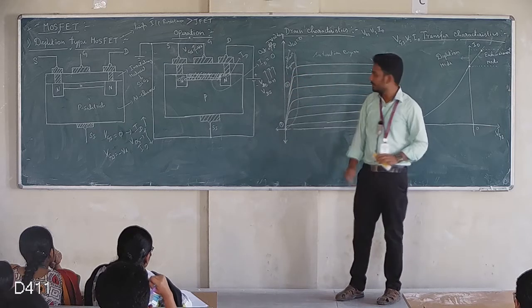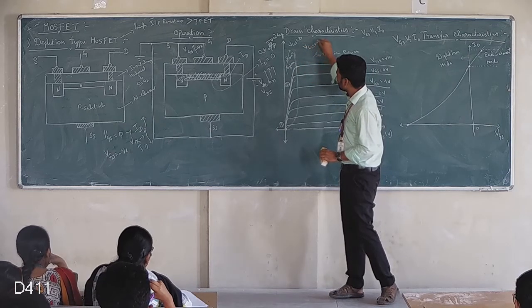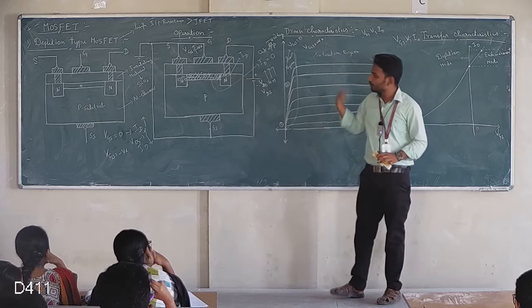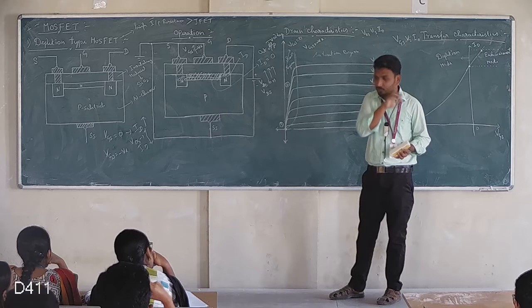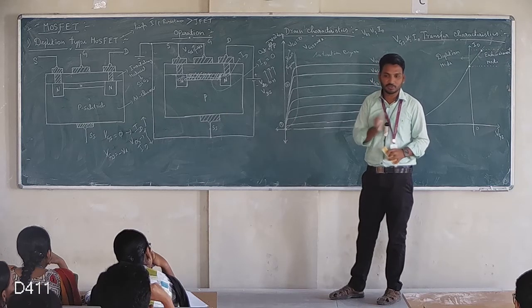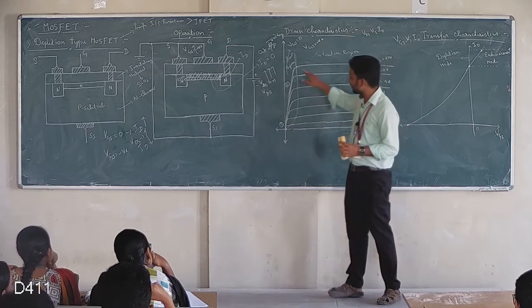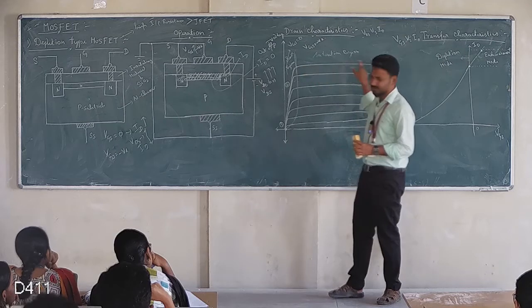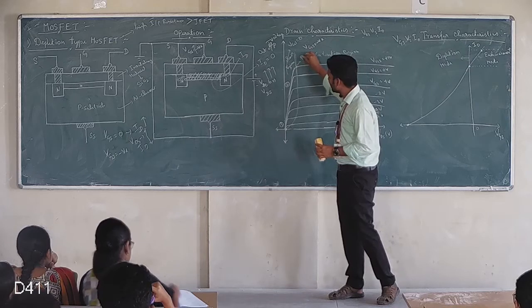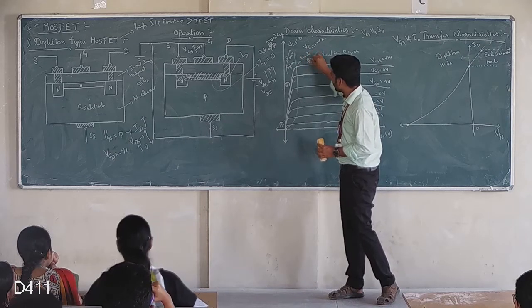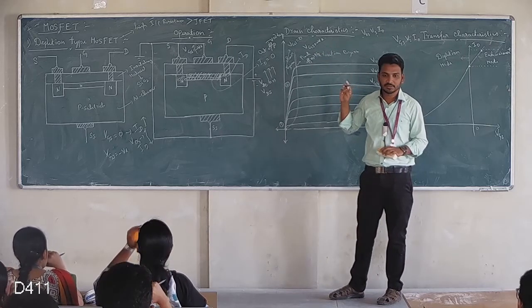Okay. Third region is VGS equal to negative. Whenever I am going to make VGS as negative, the depletion region gets formed, which blocks the path channel between source and drain. So amount of drain current will get reduced. So after this point, it will get constant. That is the third region. Okay, this is pinch off voltage, the point at which ID current becomes constant.